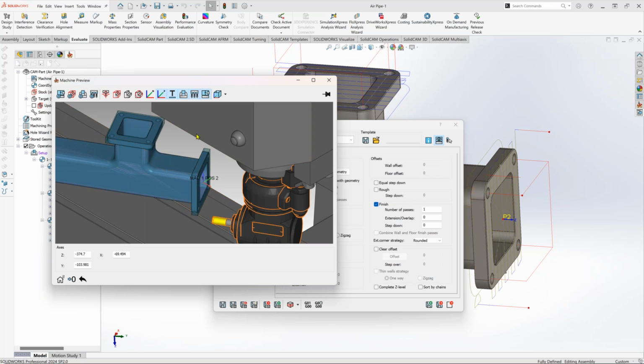Because your G-code, and it's a good reference if you're checking your G-code output or need to know what the G-code reference is, will be according to this coordinate system. Because the machine can define the position of the coordinate system but cannot rotate it. You don't have a function like this.